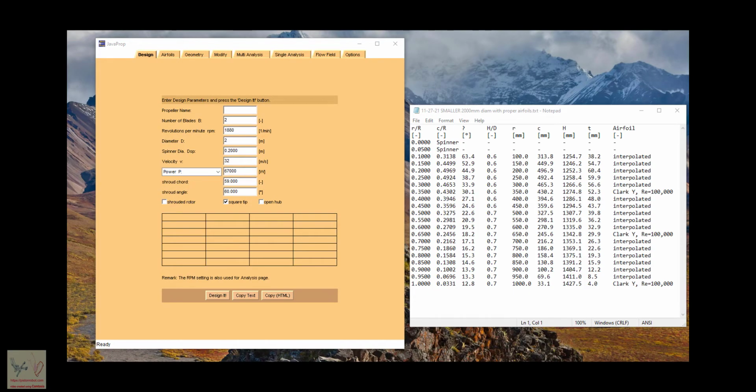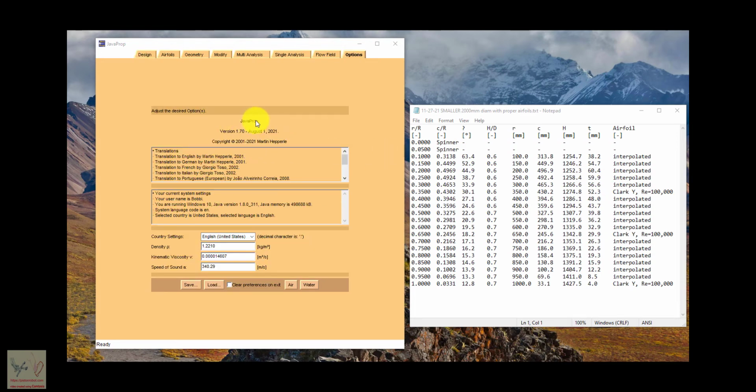And there are a number of ways to figure out what a propeller will do. One way would be to simply create it and see what happens, but that's expensive. They have worked out math where you can describe a propeller using math, and then you can find out parameters about how the propeller should work based on the math. And frequently the math is very predictive of how the real propeller will work. One program that we have used is JavaProp.